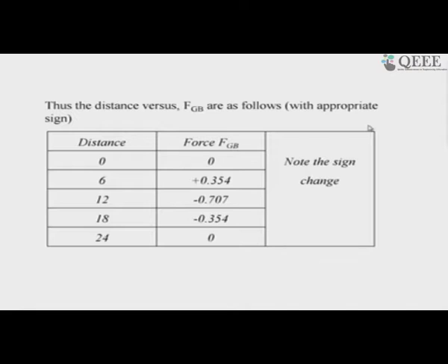So, it is the particular member force, the influence of the unit load moving, you are determining. So, that is the influence line diagram for a truss. So, influence line diagram for the force in member GB. So, it is the force in the member GB of the truss as a unit load moves onto the floor. That is the influence line diagram for the truss.